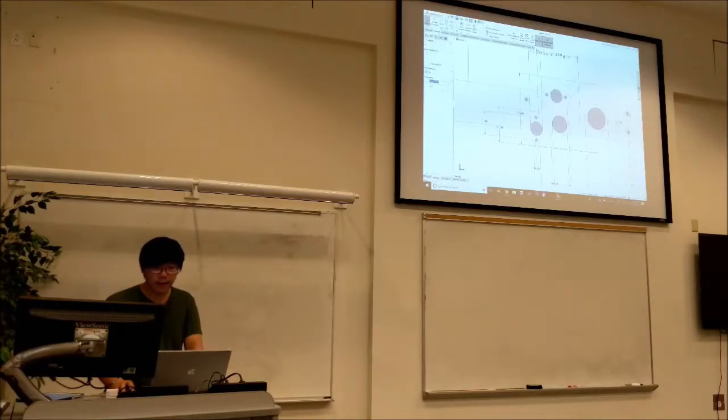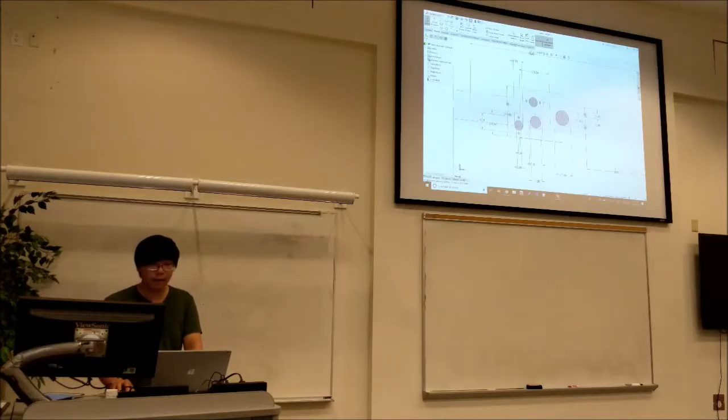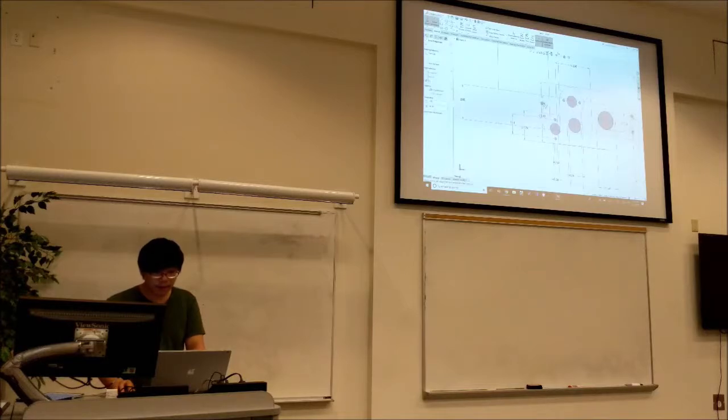So we want this to be horizontal to this point, so we can just set it horizontal. Now this rides along R2 on our hole pattern. The same thing applies. We want the distance between the edge of the tube to the standoff to be an increment of 0.5 if you're doing this type of hole pattern. So we're going to dimension this to here. And I think if we do 3.5, that looks about right.